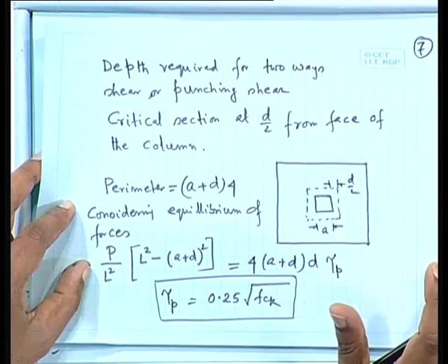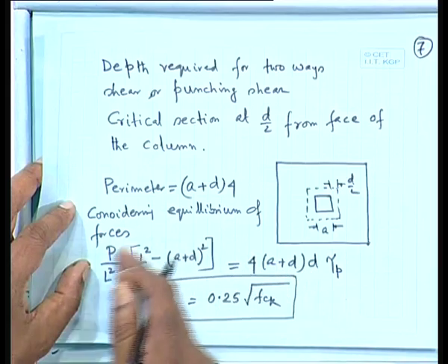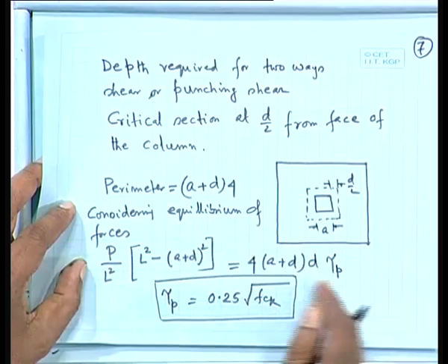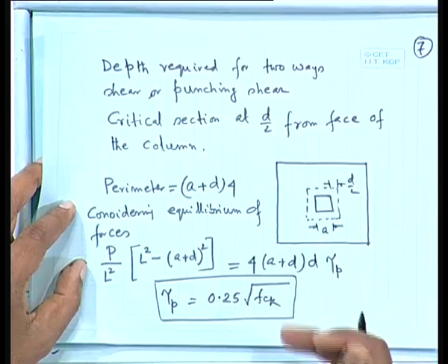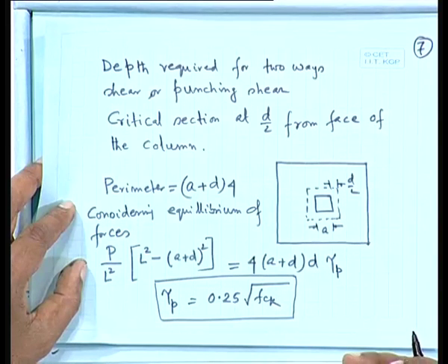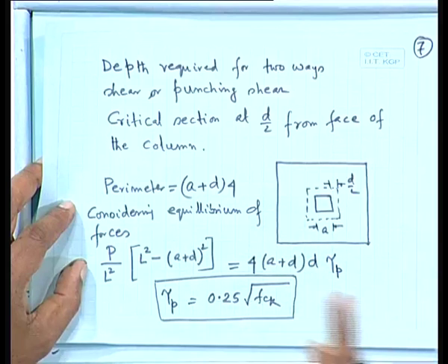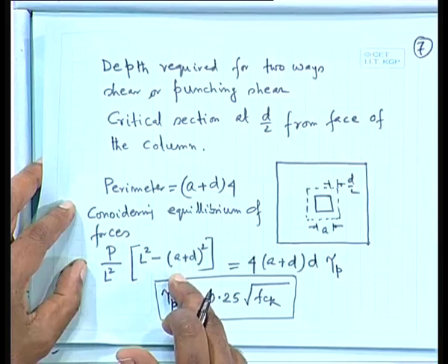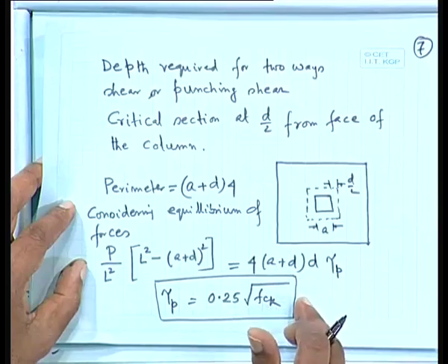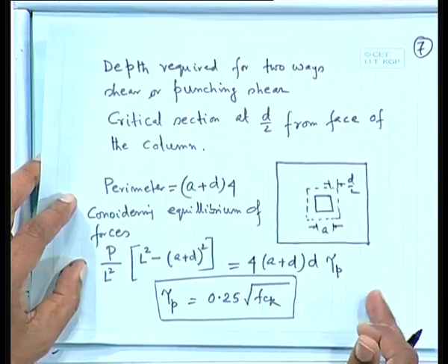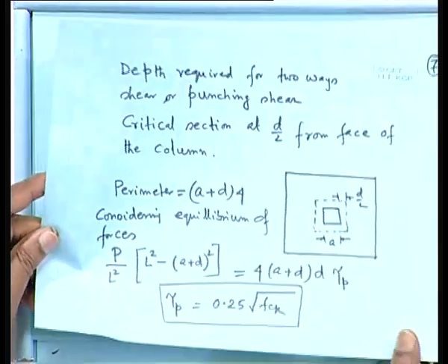Otherwise, you have to increase it. Alternatively, we can make it a full quadratic in D square and calculate D from there also. Since we already know 570 millimeter, we can keep it here and check whether that D is coming less than 570 or not.